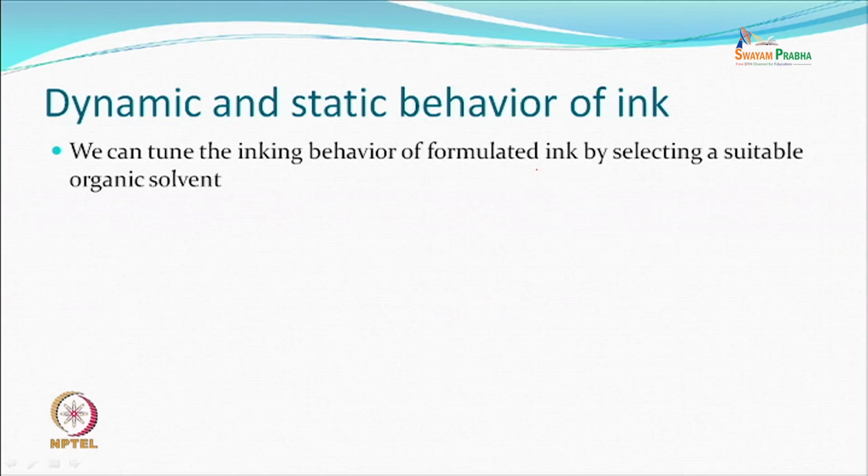After the drop has been put on the fabric, it evaporates, no problem. But when you are not printing, let's say one of the colors is not being used much in that design, or the machine had been stationary, there is a drying of the ink at the edges of the nozzle. That can become a particle, a solid material, and so it can cause some issues. So organic solvents are used.